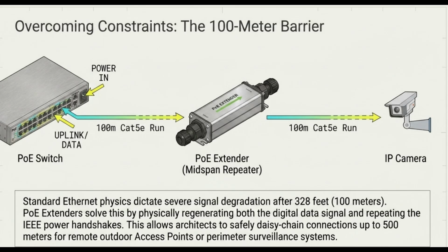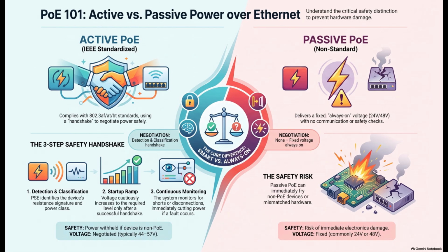It does mention that passive PoE can burn out non-PoE devices because the power is always on. Right. And it briefly touches on the existence of dual signature versus single signature power devices. But it fails to explore the practical consequences and troubleshooting steps for these critical failure points. Exactly. As a reader, I'm told the hazard exists, but I'm not told how to navigate it, diagnose it, or fix it. The suggestion here is to dedicate a focus section specifically titled something like Deployment Pitfalls and Troubleshooting that grounds all of these theoretical specifications in practical reality.